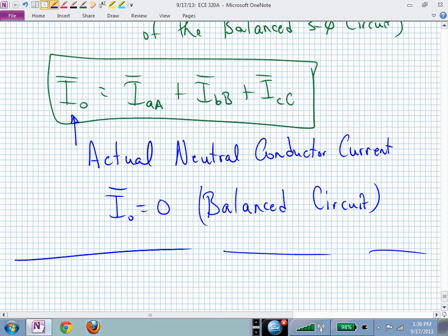Now, you know based on Chapter 9 and Chapter 3 how to convert your impedances from delta to Y and Y to delta. Knowing what we now know with the analysis, we know that the phase voltage and the line-to-line voltage or the line voltage in a Y configuration are not the same.